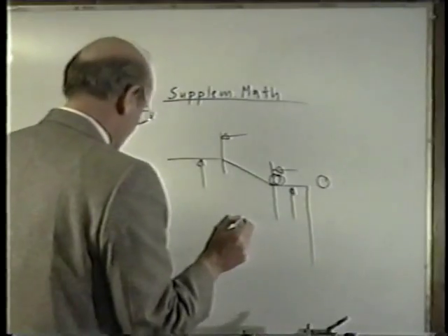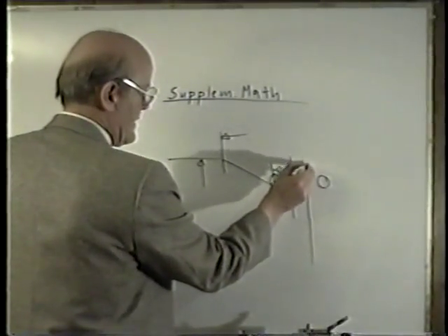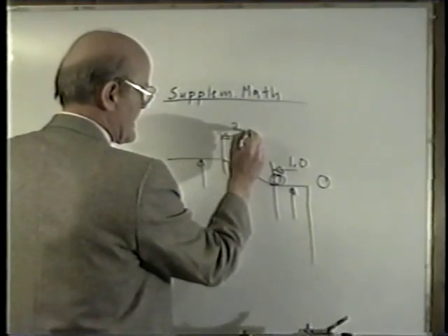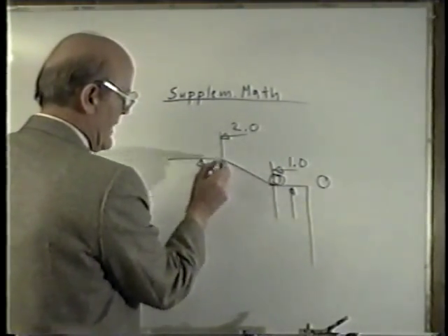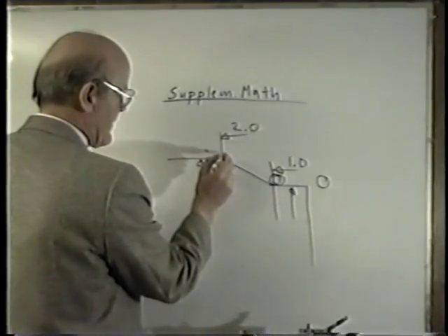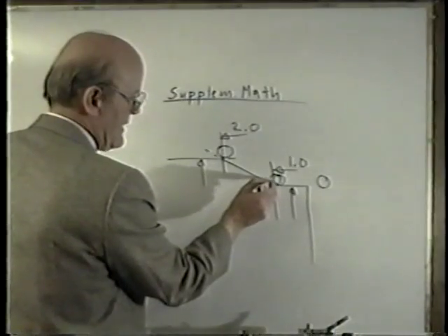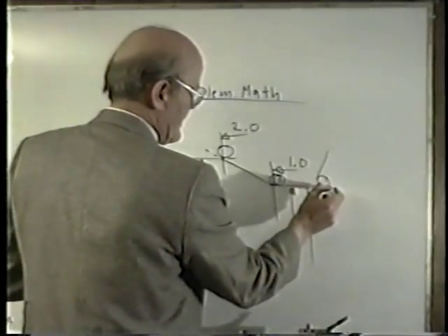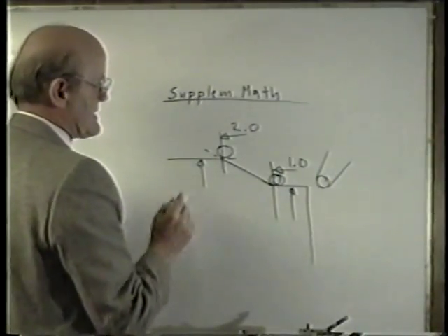So the actual program dimensions are the dimension of 1 inch and 2 inches and whatever these diameters are, but the control will have the ability to actually figure out a tangent point, something like this, where the part of this tool here has to go where it is tangent to this angle all by itself.